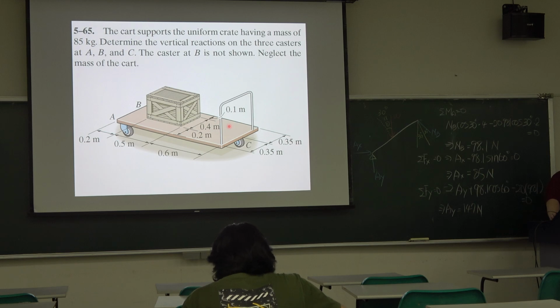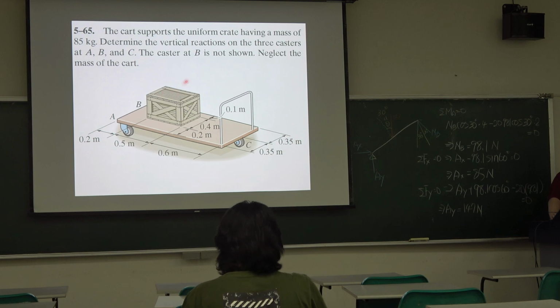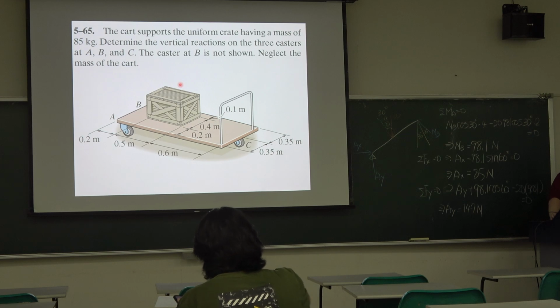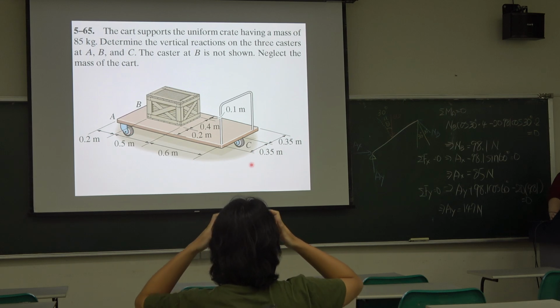like the wheel, so only one perpendicular reaction, and we can do the summations. Because the summation Fx is equal to 0, summation Fy equals 0, and we don't have these two direction forces, we just focus on the summation Fz is equal to 0. Then the MB, NA, NC force combined together